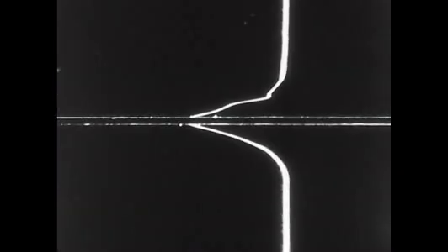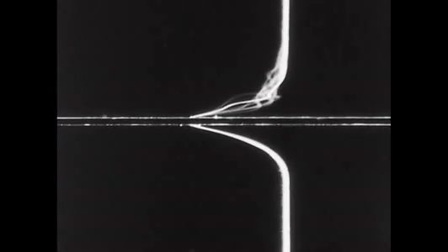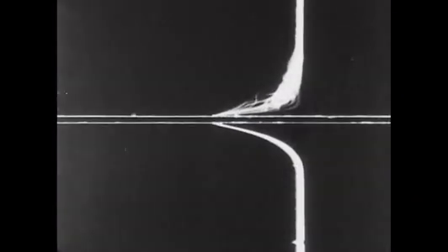Superimposing a number of displacement lines enables us to obtain a mean velocity profile for the turbulent layer and the laminar layer, and at the same time gives an experimental notion as to where the fluctuations occur and how large they are in the plane of mean motion. In this photograph, we can compare mean laminar and turbulent profiles. Here is the laminar one, the turbulent one, and here they are superimposed.